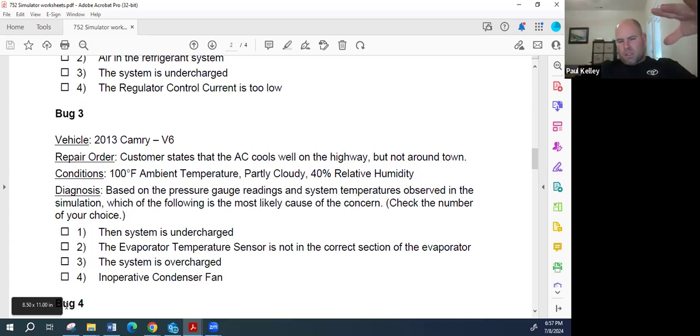So if my job is to pinpoint the root cause, right? Now, did I see some other things? Yeah. And did I say, well, corrosion on the battery terminals, that could cause some issues? Yeah, that could. However, corrosion on the battery terminals would cause a voltage drop. And a voltage drop could be an issue, but for the cart not to move, it'd have to be a massive voltage drop, like an insane voltage drop. If the cart's a little slow, if it's a starter on a car and it's cranking slow and you see corrosion on the battery terminals, that could make sense. But you could measure that, right?